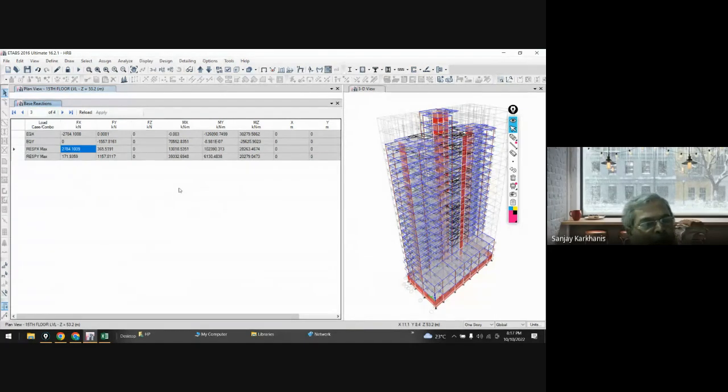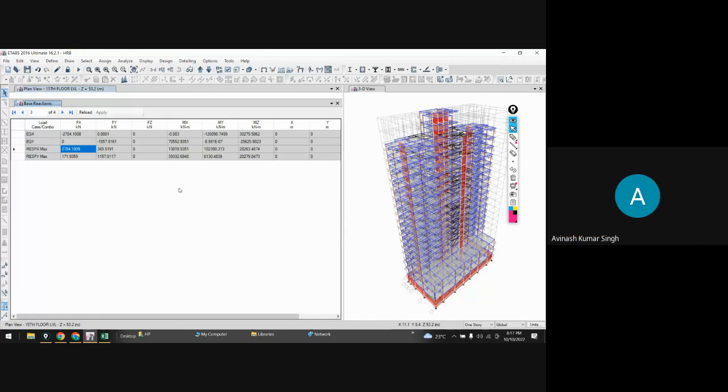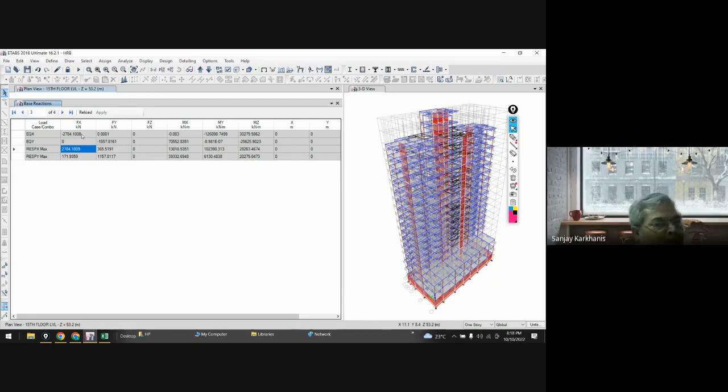For analysis you don't have to worry about it, because it will not make a big difference. But if there is a facility, why not use it. No no, that is fine sir, I just wanted a confirmation of what to do if this ever happens in a model. See, if you are not using these 4 digits, then your scale factor will change, and if you go for this result using another scale factor, you will again find the difference between EQX and Spectra X, or EQY and Spectra Y. If you accept some difference, then it is okay.